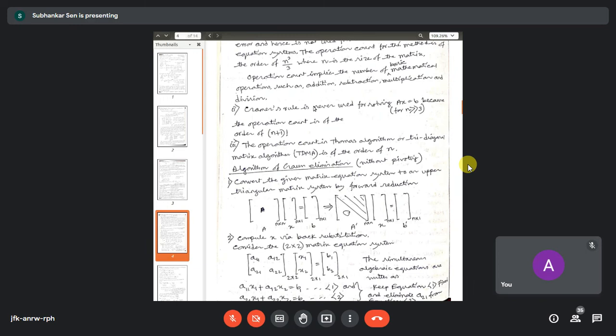And for the convective term on the left hand side, or the advective term, you don't have any choice other than backward differencing. Backward differencing is known as the upwinding scheme when you talk about fluid flow. So you have to take backward differencing at least of second order.